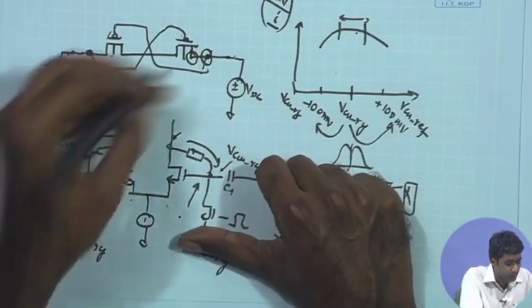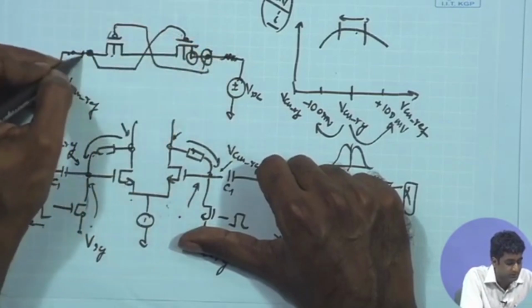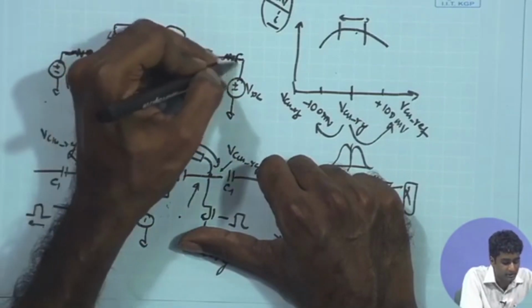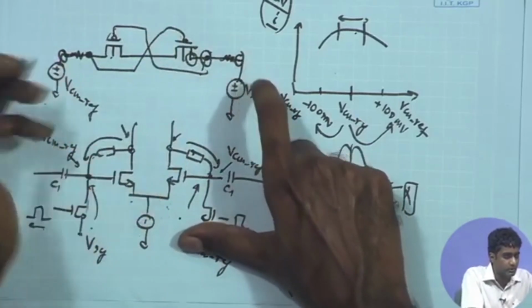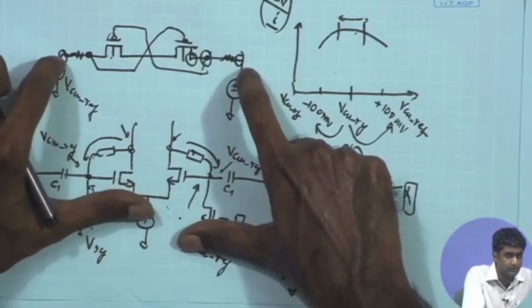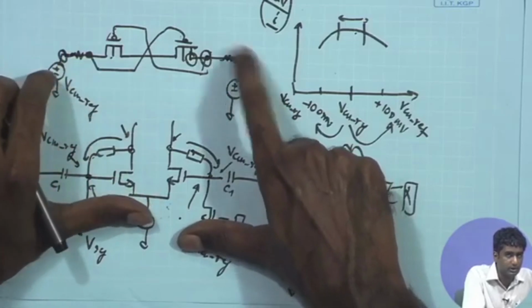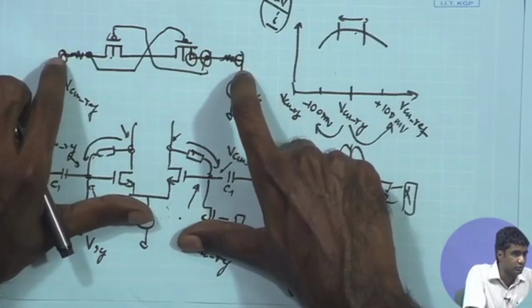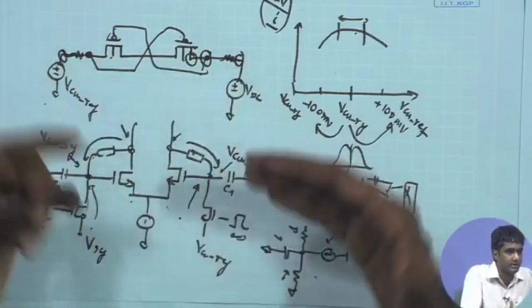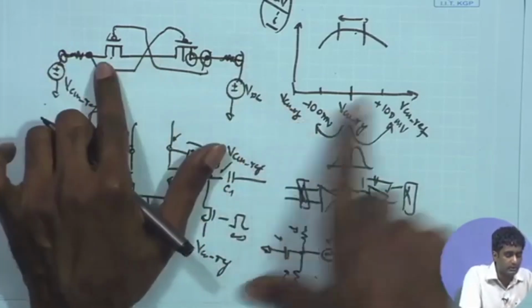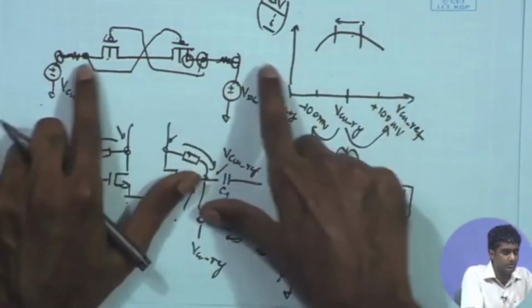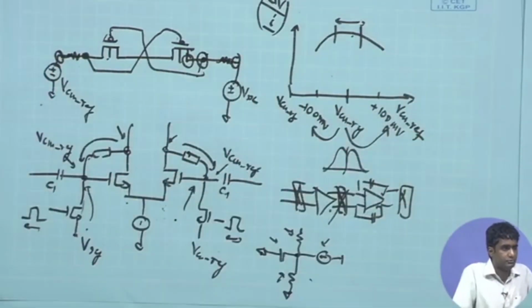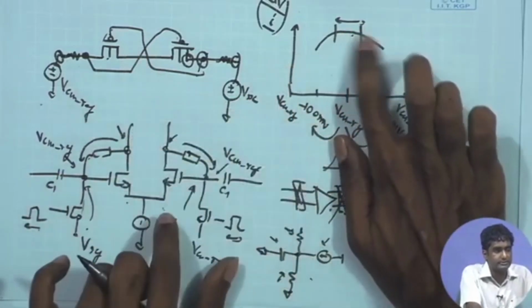The better way to do it is to put a small resistance over here, and then measure the current flowing here and measure the current flowing here, or even from the sources you can select the upper terminal of the sources in the simulation. That will also give you the current flowing through both the sources, so you can check how different they are. In the central region maybe it will be very close, but as you diverge from this, it will become different. So this scheme will be valid only for this central region where other